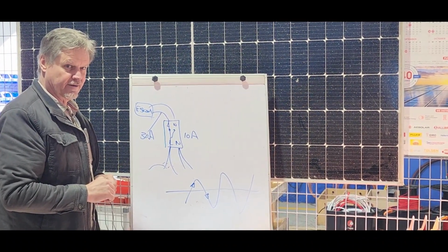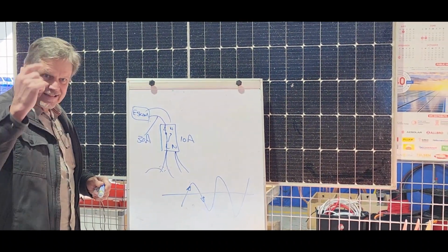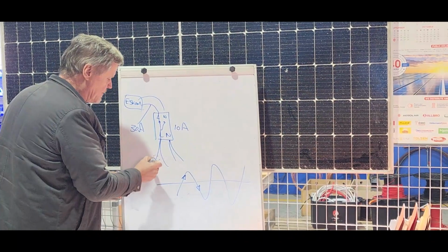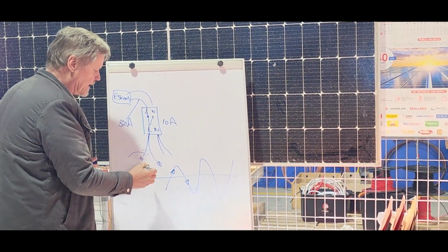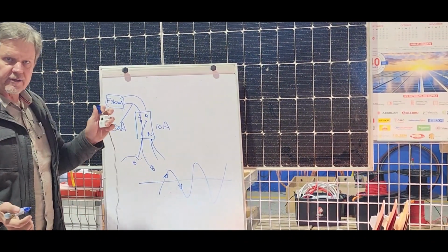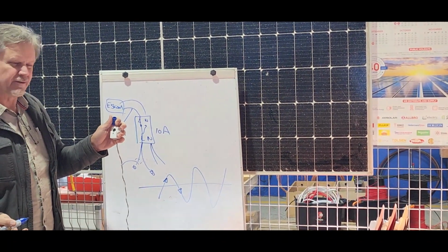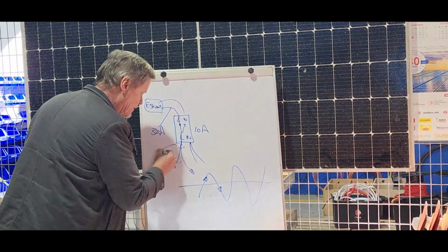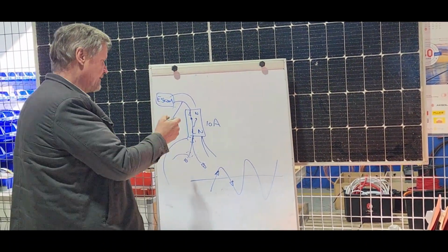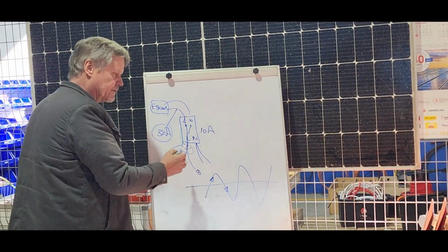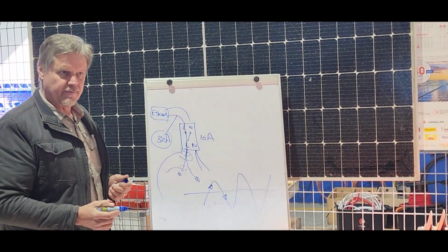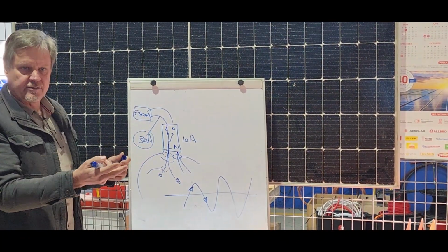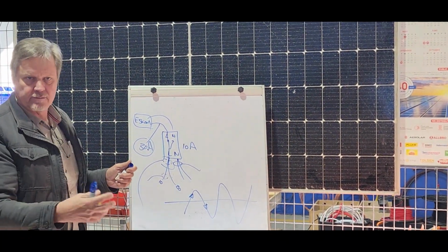I think the current is still the same current that is flowing on both of them. Yes. So if there's 30 amps running there, maybe this cable has 30 amps and that cable has 30 amps. So if I just catch the one cable, I'm not going to measure the entire current. You get it? So you can put the CT around both those cables, and whatever amps you measure there is the same amps you measure there. Or you can put the CT there, then just know that the directions are swapped because you're measuring the in and out differently.